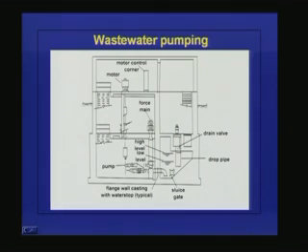In some installations we can put the pump directly in the wet well and then pump the wastewater out, but here we keep the pump in the dry well and take the suction pipe from the pump to the wet well, so that water entry from the wet well into the pump is through this suction pipe. Here this is the motor and the power is supplied to the pump, this is the pump center line and this is the delivery pipe from the pump.